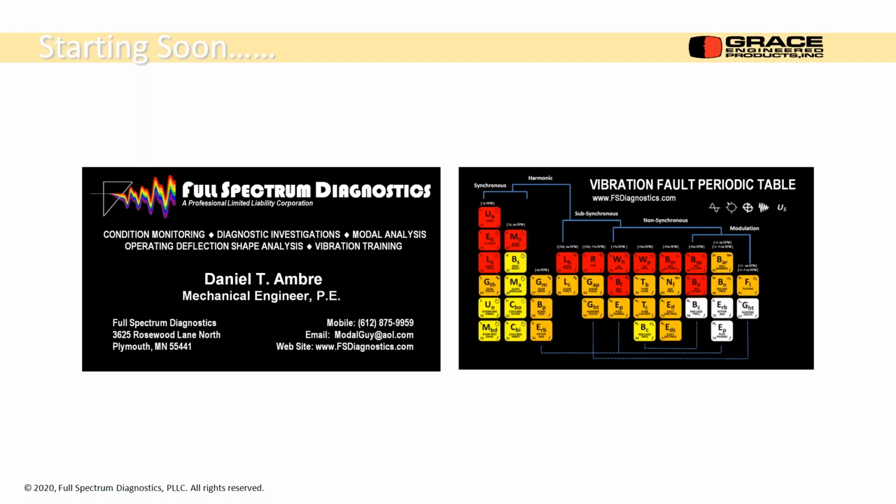Can you help me define the instrument range calibration? Define the instrument calibration. Are you talking about the millivolts per G? If that's the case, it comes on the literature from the transducer, and it'll be close to 100 millivolts per G, but it might be 98.4, and you put that in, and that's the exact calibration factor for the transducer. Yeah, that's what he was asking.